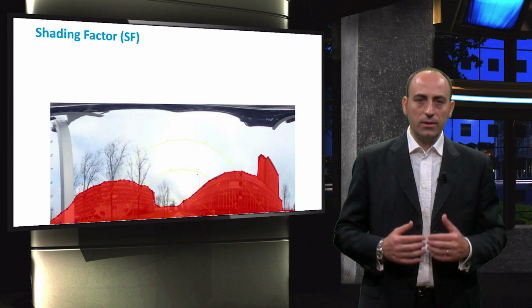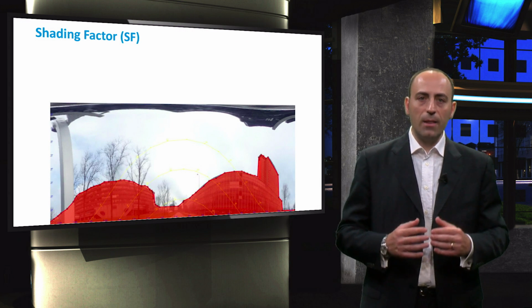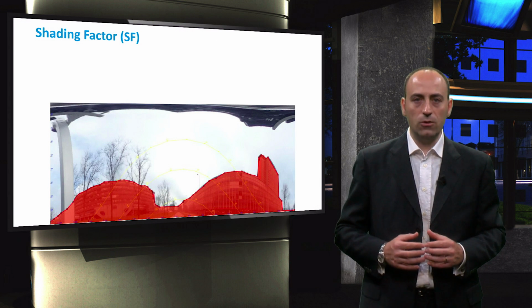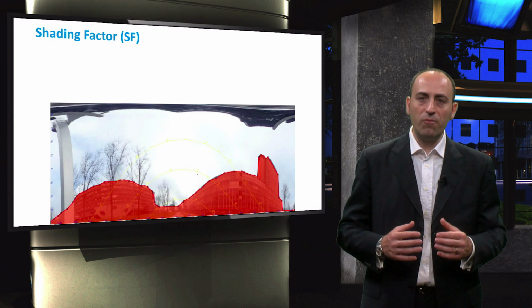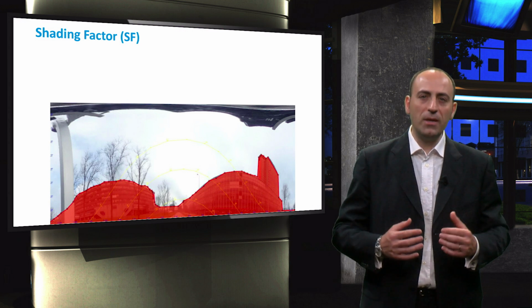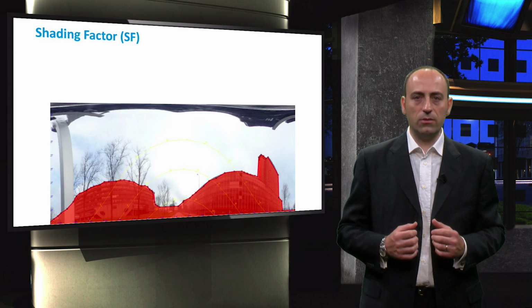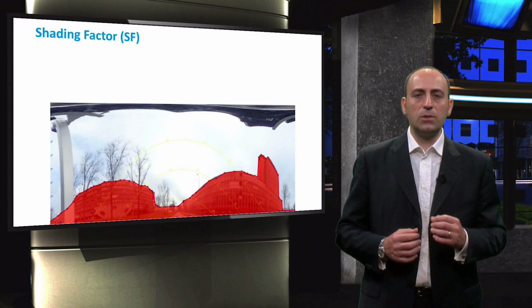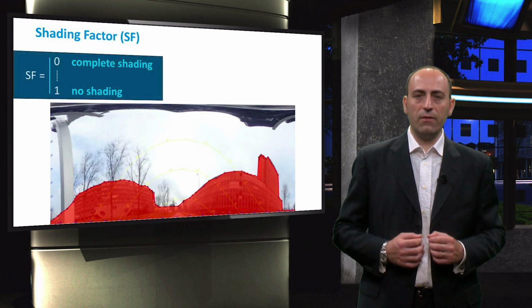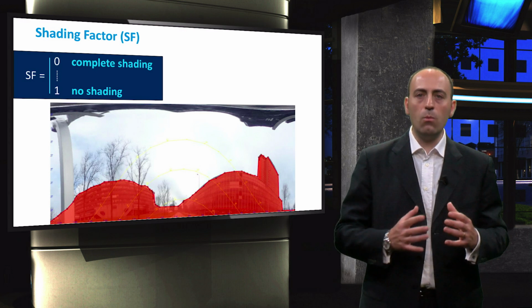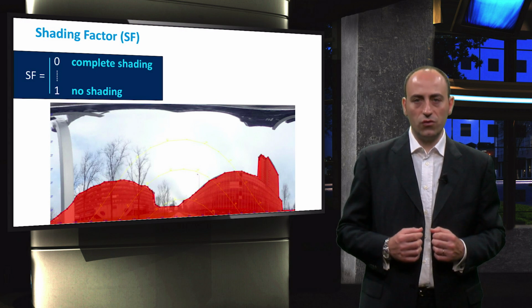In this example at the TU Delft campus, we picked and placed points on the edges of all the objects visible in the sky dome. Actually, for the sake of precision, trees should also be considered, but it is a bit tricky to highlight them with this method. Then, based on the area described by those points, it is possible to find the so-called shading factor, which is simply a number that varies between 0 and 1, as a function of time.